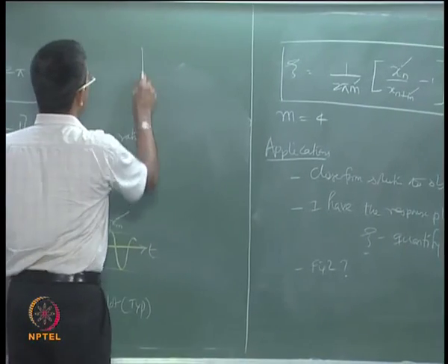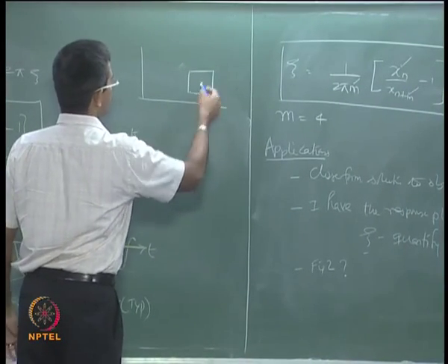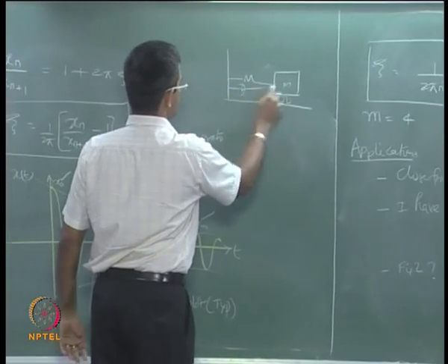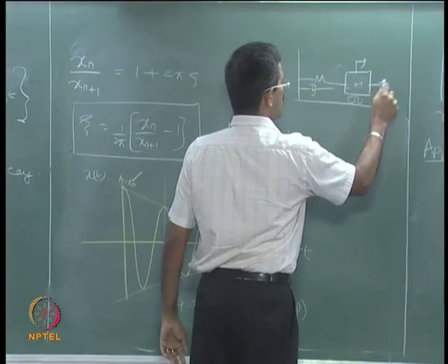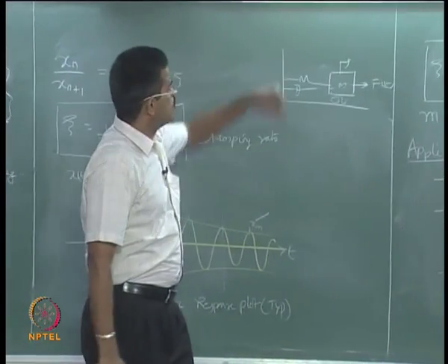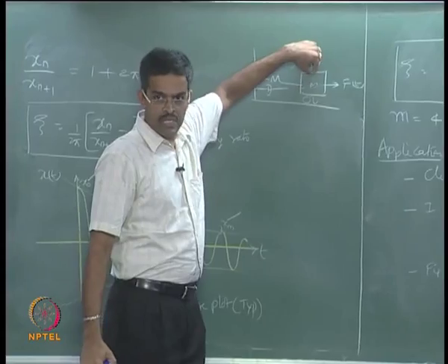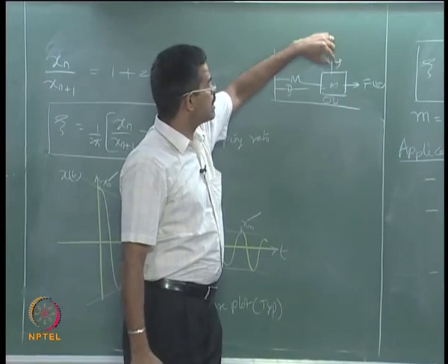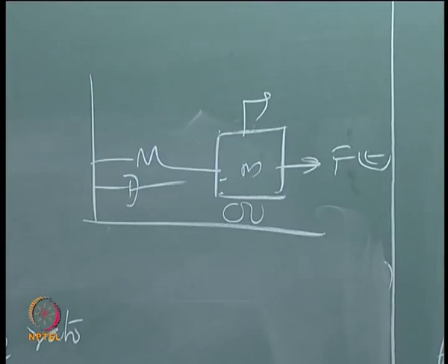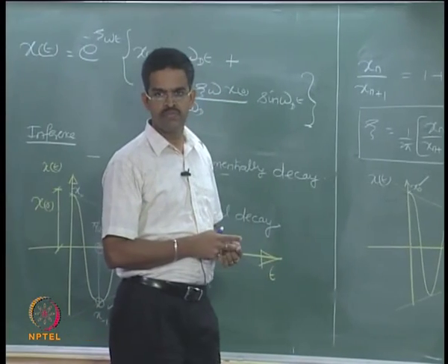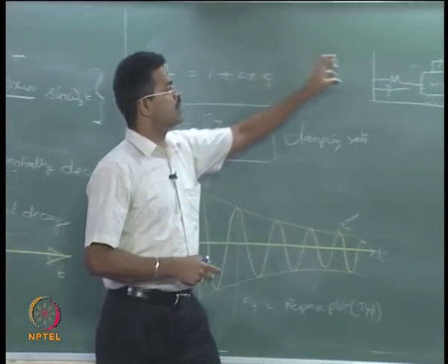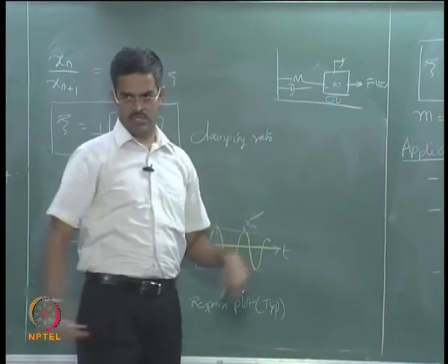You simply have a model which is an idealized single degree or multi degree, whatever it may be, apply a free vibration to this, put a displacement transducer and accelerometer here, directly record the time history vibration of this mass in a time scale like this. You will know what is the damping imposed on the mass under the given working condition.